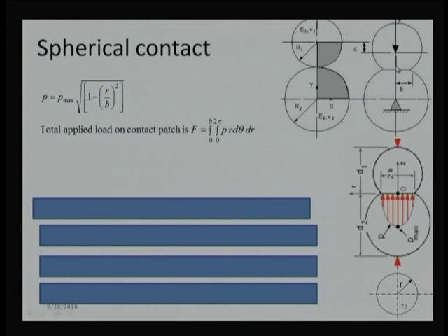And when this kind of deformation occurs, you can see there will be a contact area, and that contact area, in this case particularly sphere versus sphere, will be circular. If there is some sort of misalignment, it may be elliptical, but here it is mostly circular, and we are assuming that this radius R goes from 0 to the max value of B, where the maximum deformation occurs.